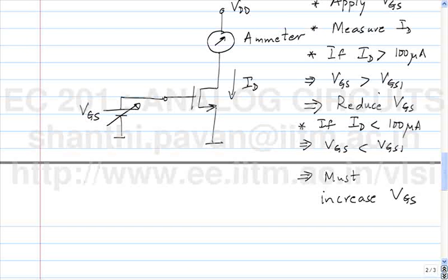In the second method, where we measured the current through the MOSFET and varied the gate source voltage, did we need to make any assumption on the nature of the device? If it was square, if it was cube, what would happen? In the first case versus the second. The way of doing it with two VGSs and then finding the characteristics assumes that you already know the characteristics. On the other hand, the second method, where we just monitor